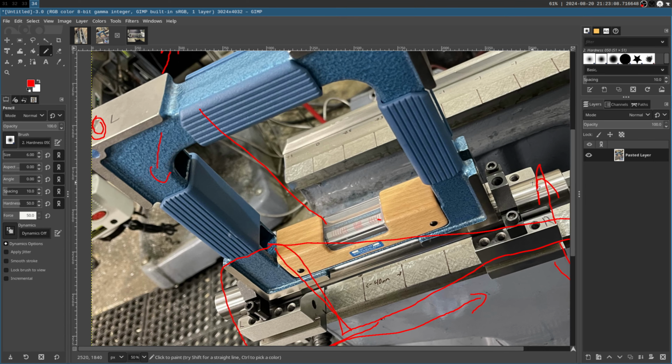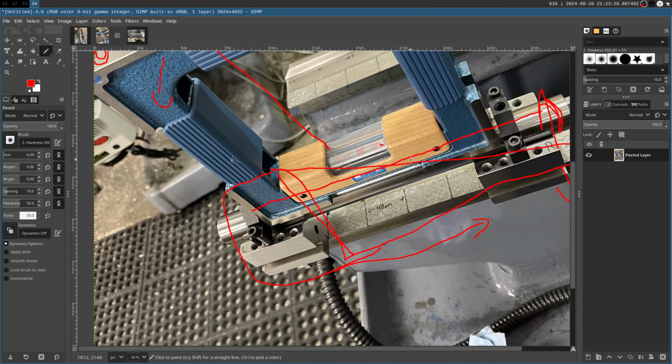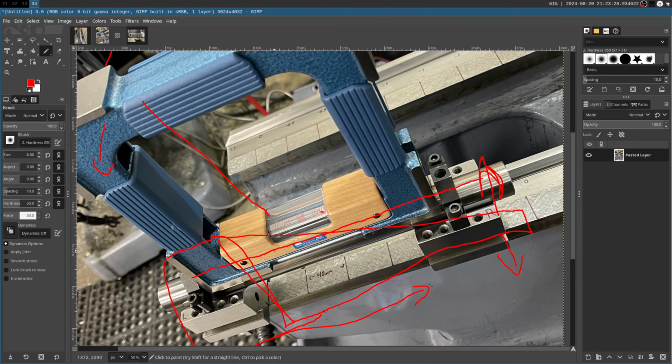Really what I'm looking for, I think, is the concentricity and the flatness of the top bar, because in theory, the level isn't always going to get set on top of the bar at the same spot. It might slide backwards and forwards a little bit, and thus if the bar is off, that would affect things. But that's really it. Since the bar is rigidly clamped to the V blocks, that is a rigid setup, so that is all accounted for.